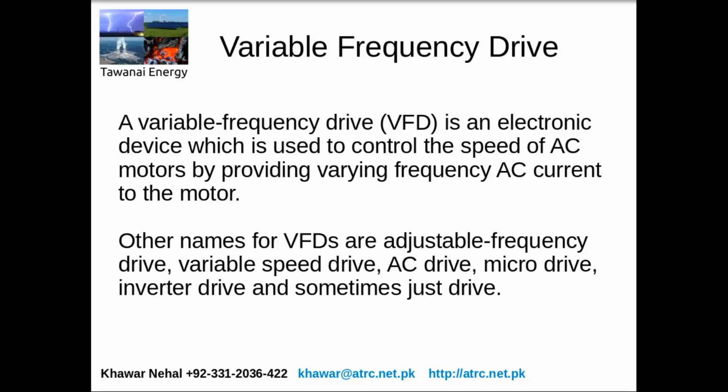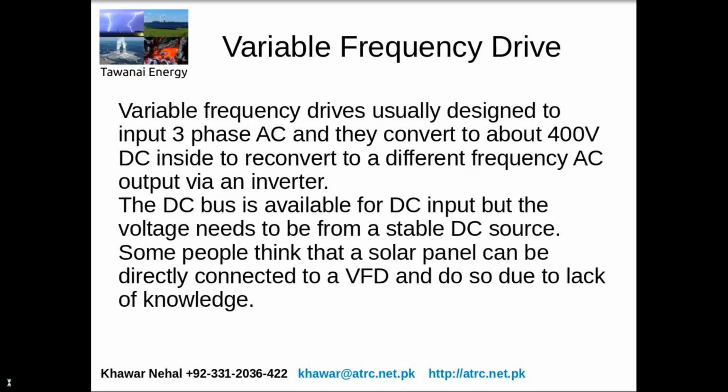The issue is that with AC motors, if you change the voltage, it doesn't really affect the speed of the motor. The only way to change the speed of the motor is to change the frequency of the AC current that's going into the motor. And there is no easy way to transform AC current, so what people do is they convert the AC through a rectifier into DC, and then the DC is converted through an inverter back into AC. But since you are creating the AC current in the inverter, you can select which kind of frequency you want, so the combination of the rectifier plus DC bus and the inverter component is called a variable frequency drive.